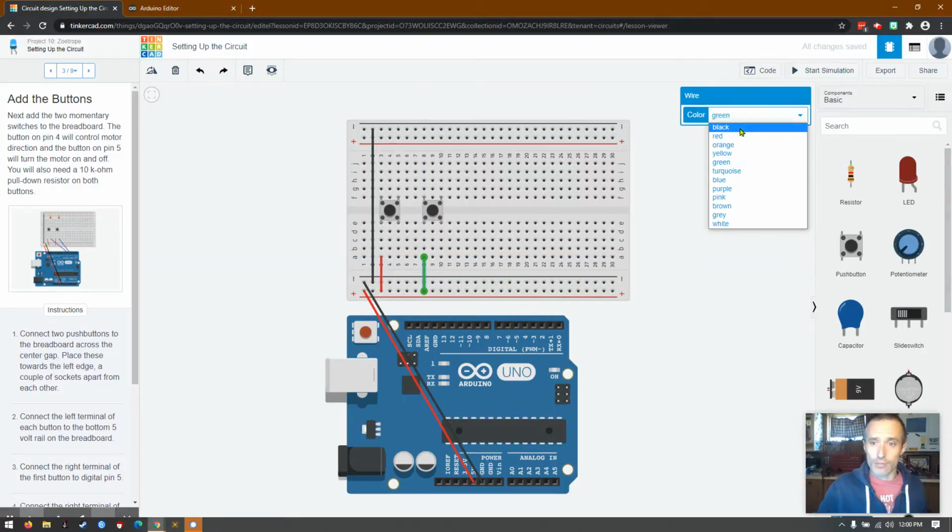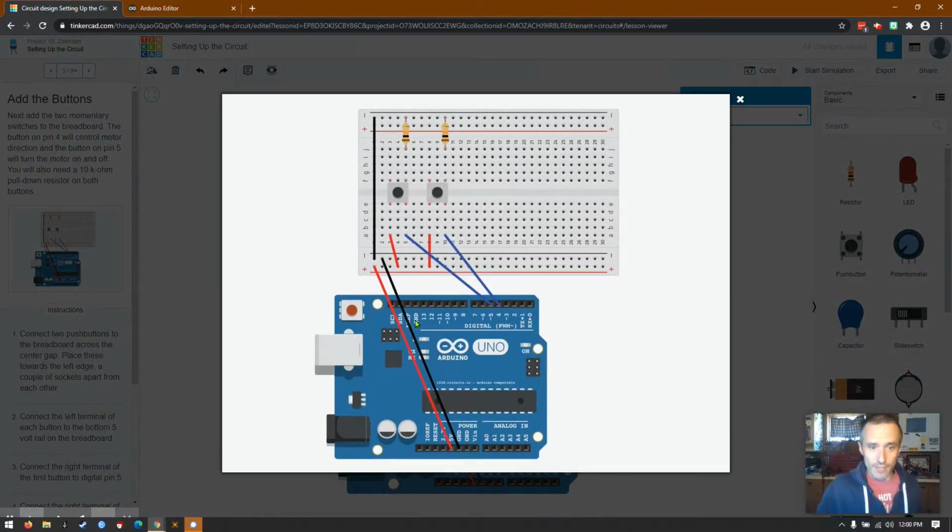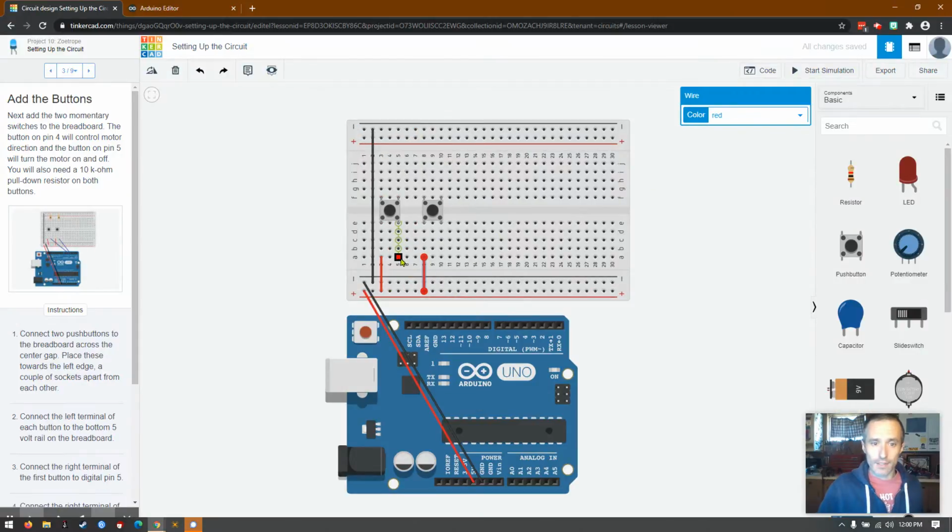Remember, you're in charge, right? As long as you hook it up to anywhere on this rail, you're good. This one, they moved over. I'm not sure why that was, maybe just visually. This one's going to run from 5 to 5, and then 10 to 4. So we've got 5 running to 5, 10 running to 4. They made them blue. The reason why they're not red or black is because they are not positive or negative necessarily. They are part of a different circuit.